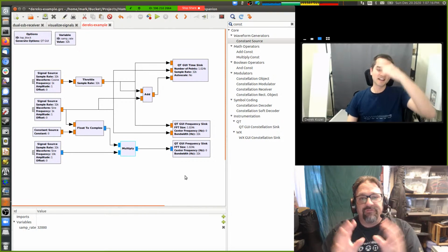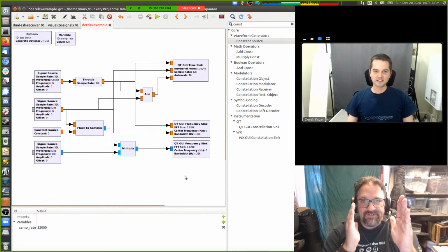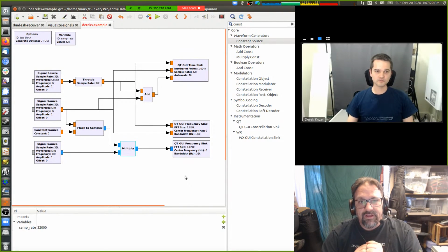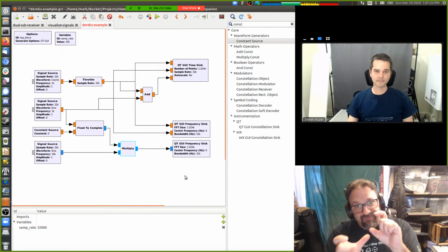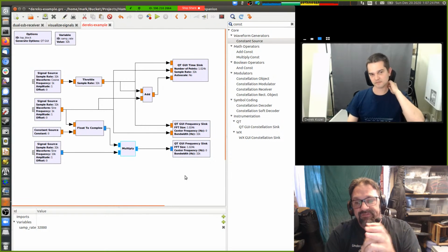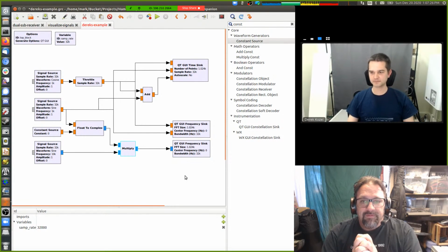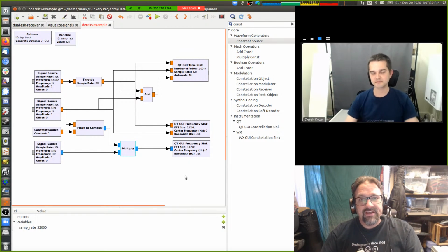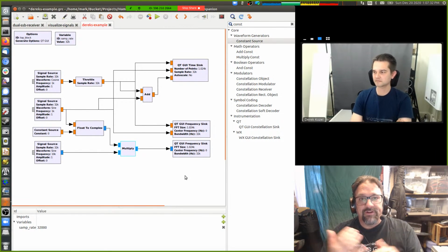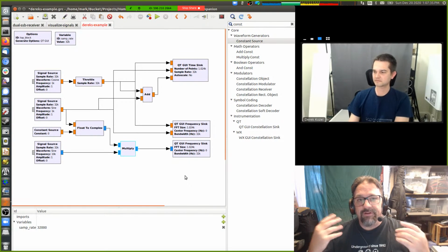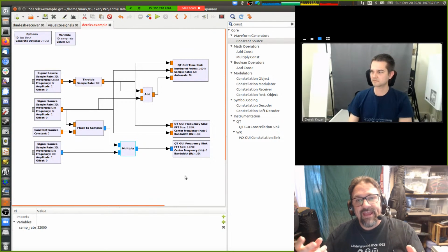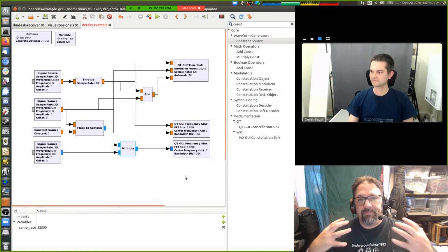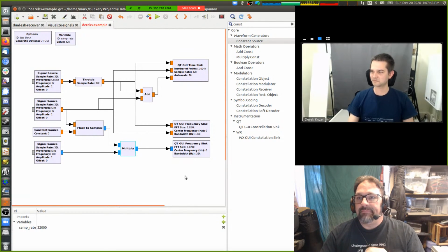With math, you can convert back and forth between this amplitude of a sine and a cosine and the ultimate amplitude of the signal and the phase of the signal, the time shift of that signal. It's still 2 numbers, right? Exactly like you described. It's rectangular versus polar coordinates. It requires the same amount of information to represent the same thing. It's just a matter of what format those numbers take and how they represent the signal. So that makes a lot of sense.